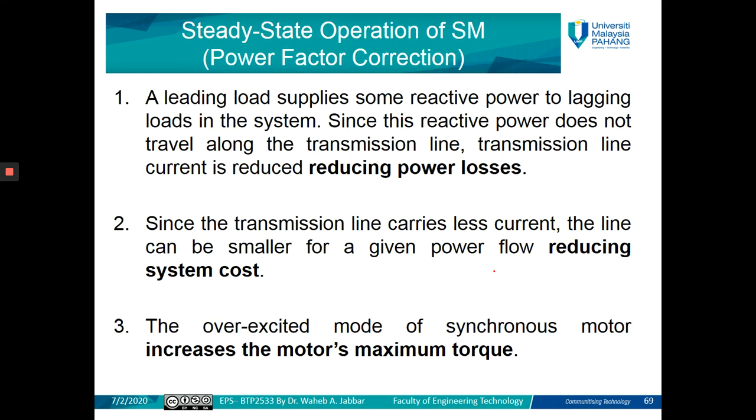It is good to have a leading power factor rather than a lagging power factor for the following reasons. The first one: the leading load supplies some reactive power. If you have a leading load, like a capacitor or a synchronous motor, it will supply reactive power to the lagging load. So there is no need to transfer reactive power from the power station to the load, because it will be locally supported by an existing reactive power source like a capacitor bank or a synchronous motor.